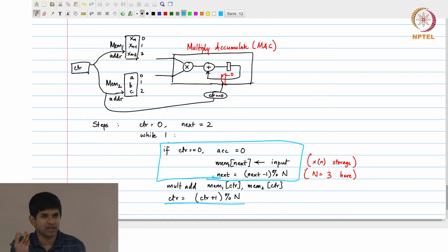Even from the point of view of hardware, that's a bad idea, because it's going to consume a lot of energy, because of toggling of inputs. Let's say that I have a 100 tap filter, there are 100 elements that need to get shifted, a whole bunch of bits toggling, whereas what I really need to do is keep 99 of them the same, throw out the oldest one and replace it with the newest one. That's what I'm doing here.